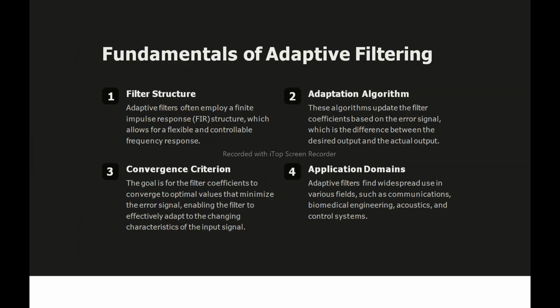These are the four fundamental components: filter structure, adaptive algorithm, convergence criterion, and application domain. First of all, filter structure. Adaptive filters often employ a finite impulse response structure, which allows for flexible and controllable frequency responses. And then the adaptation algorithm.